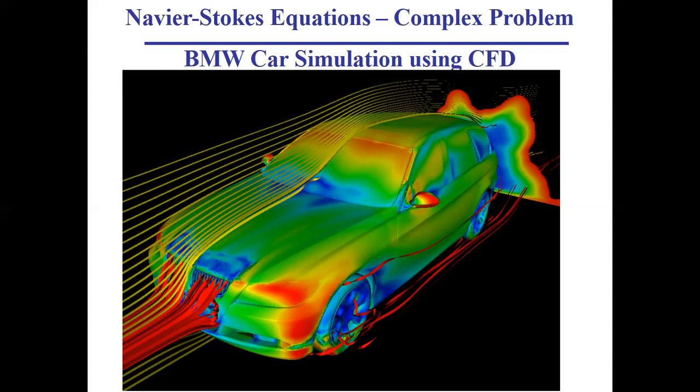So how to do this? I can run a simulation. I draw the geometry of my car and put it in a wind tunnel, let's say, with a flow coming over it. If I'm using CFD, I can plot contours for the velocity profile. When the flow hits the car, you will have flow separation, and you will have formation of boundary layers around the car.